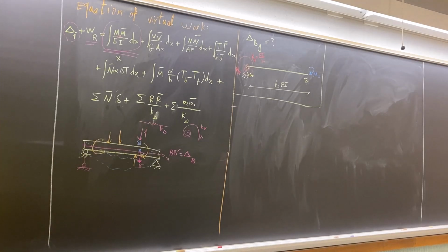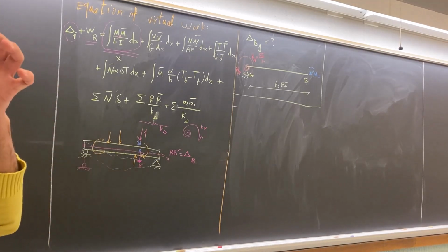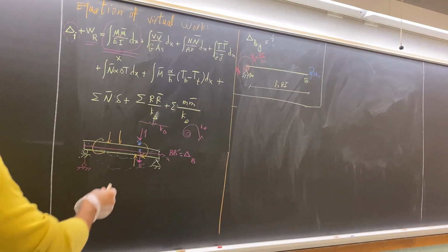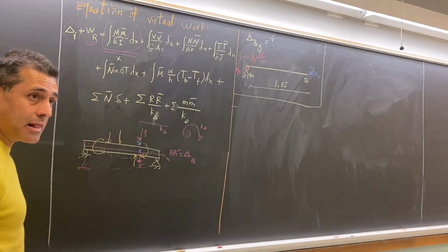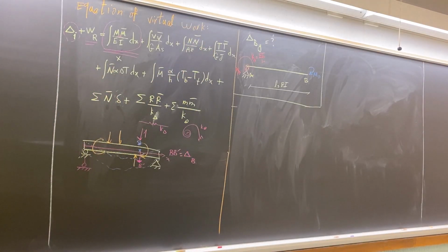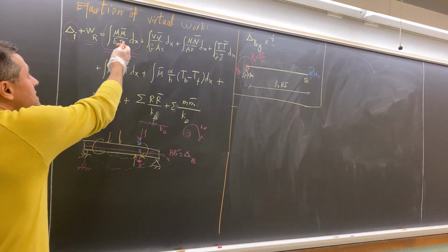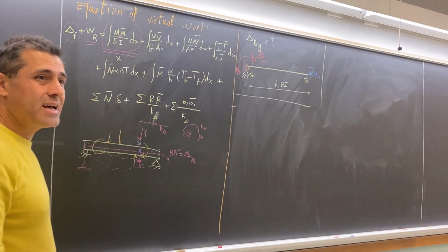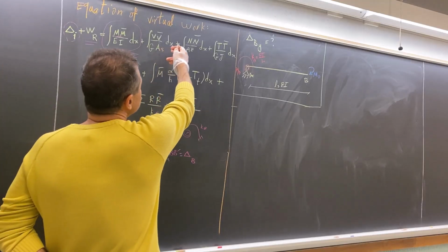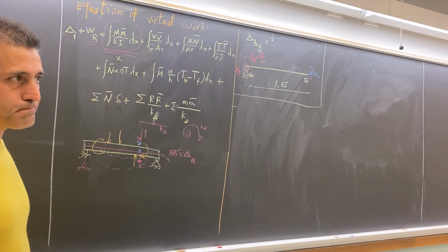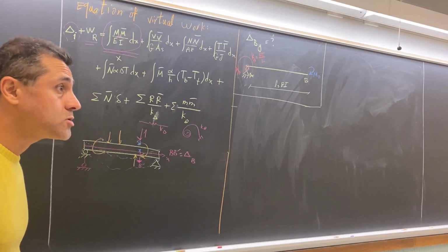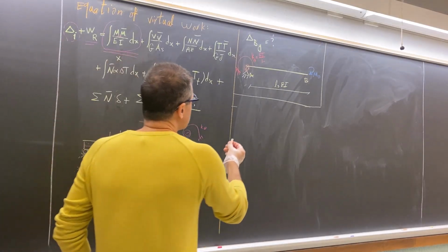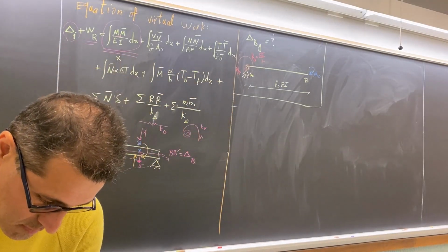We apply the method of virtual work. Before we get into the formula, because the effects of shear force and normal force are negligible in most cases, the question tells you that you only use the first term. Remember the textbook I showed you? The textbook is using only the first term because in most cases the effect of other terms is negligible. But sometimes it is not, so the question will tell you. In this case, we are just using the effect of bending moment.